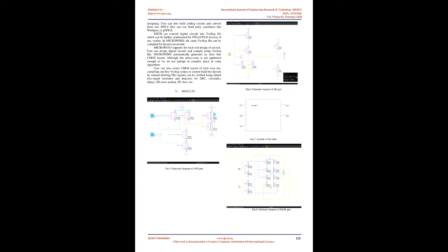2n-bit result. Function and algorithm of modules. 2's complement generator. Function: the 2's complement generator takes the multiplicand MD and multiplier MR as its input and produces MD' and MR' as its output in case of negative numbers. Algorithm: 2's complement is generated by inverting all bits of the multiplicand and then adding 1 using a ripple carry adder.